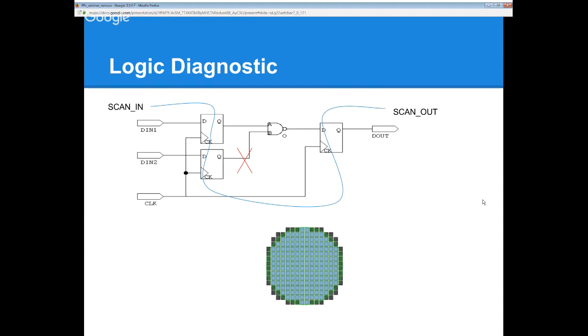We can get many chips from one wafer, and we test every chip. Then we get every result and summarize this failure information. If the defect is random, the failure is also random.